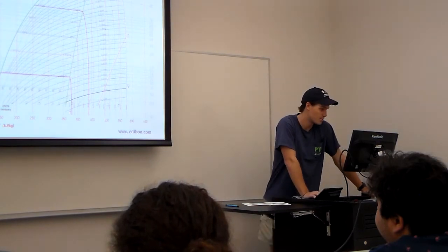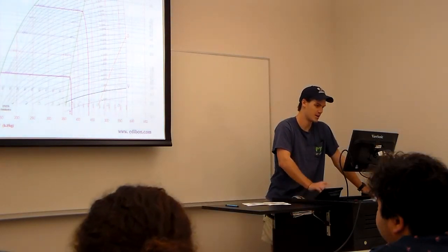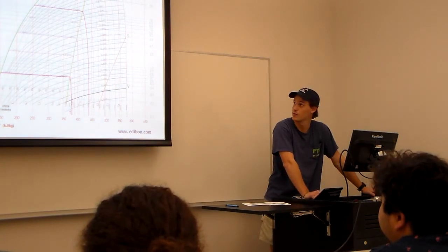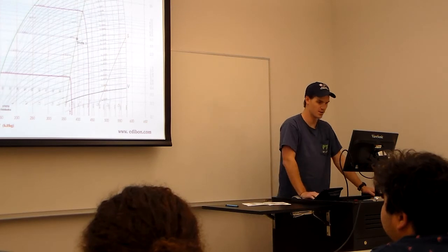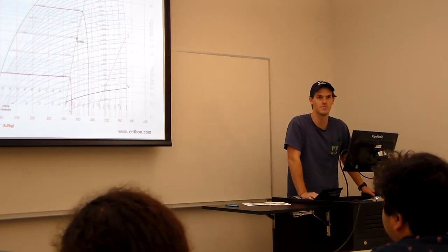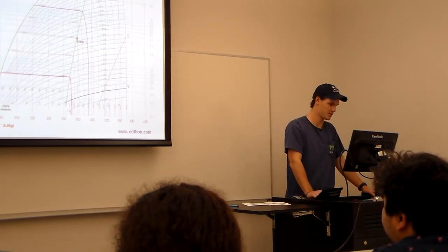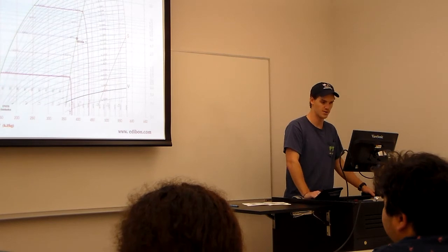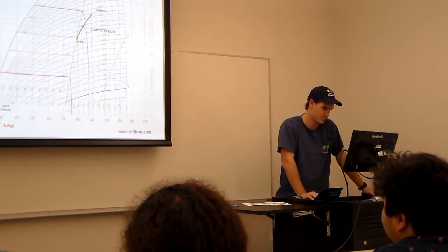So here's a refrigeration cycle on a P-h diagram. I'll go through it. Right here we have a P-h diagram of R134A, our refrigerant in our case, and our state 1 hypothetical is there. It's on the saturated vapor side of the vapor dome, as is given in the ideal case. From state 1, we move to state 2 through a compression cycle through a compressor.